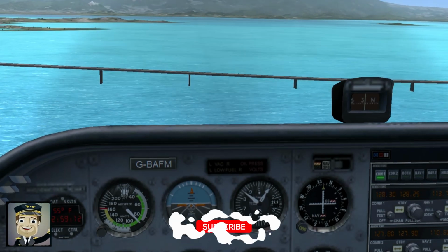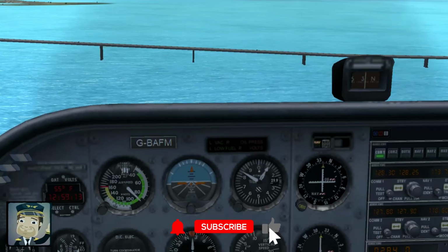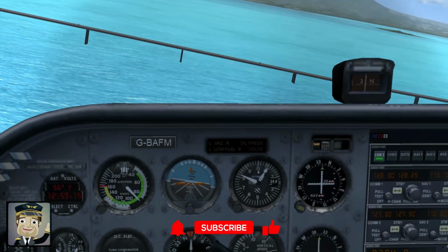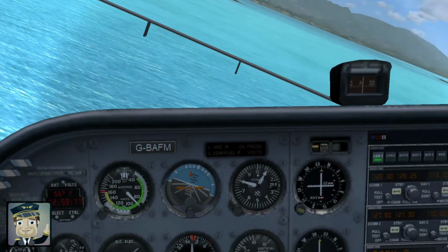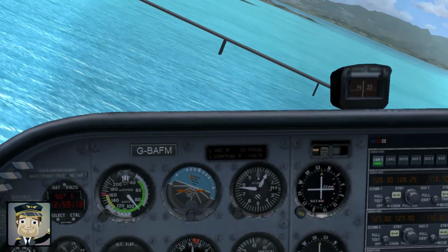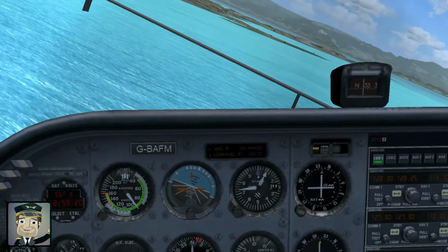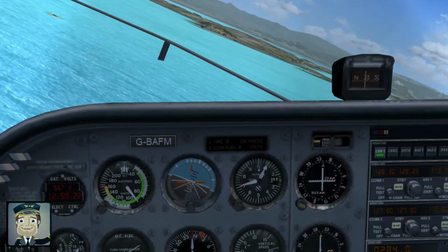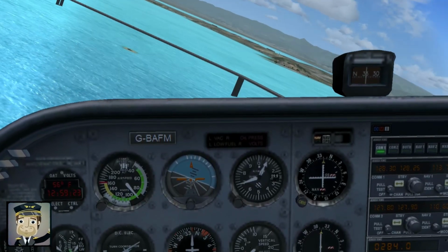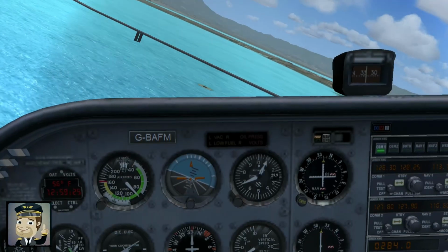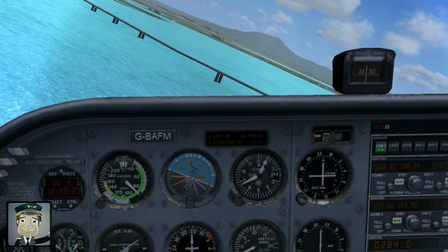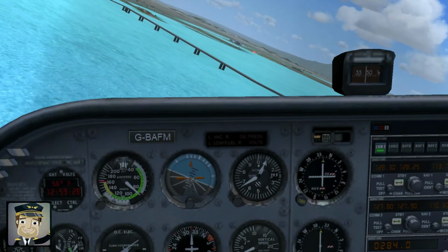Wind awareness becomes even more important here. A tailwind on base causes the aircraft to cover ground faster than expected, requiring quicker adjustments during the final turn. A headwind, on the other hand, stretches the time spent on base, making the descent feel slower. The pilot must anticipate these effects to avoid overshooting or undershooting the final turn.